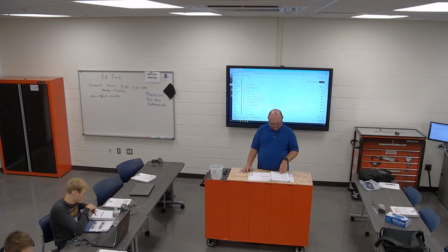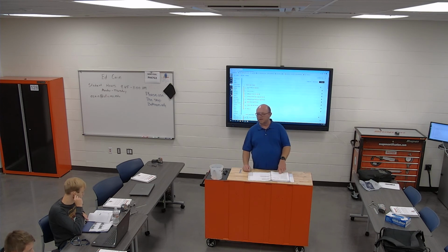1 divided by TPI. So say I'm doing quarter 20. It would be 1 divided by 20 times your RPM. And we usually run, we teach you all in this class, we run them at 100. Usually just every one of them, because it makes the math really easy.